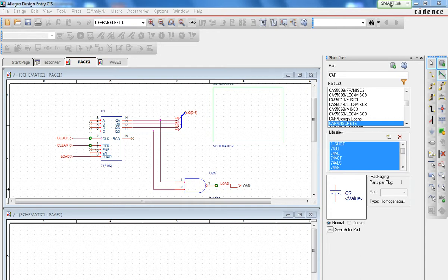Alright, lab 4-4, processing design. Lab objectives. After completing this lab, you'll be able to open a schematic and annotate part references, view the results lists of annotated part references, run the design rules check, annotate intersheet references, cross-reference parts, create a netlist, and create a bill of materials. So what we're going to do here is open the schematic, which I've already done, as